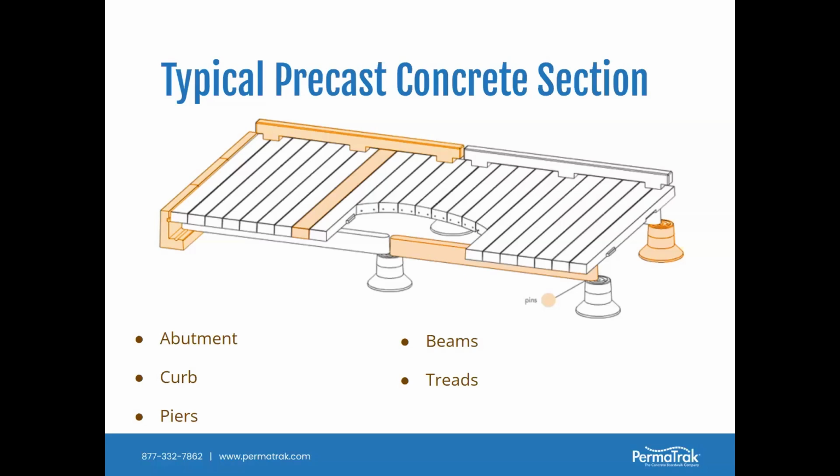So think about that original slide we showed you about where you put the boardwalk and what the impacts are to the wetlands. Think about how fewer piers is less impact, right? So that may become important to you. And then lastly, the perpendicular component, or the surface that you're walking on, is what is referred to as a tread. That is the plank, if you will. If you're familiar with timber boardwalks, that would be the plank. It would simply be a plank of concrete. And then typically a curb or a railing would be set on top of the system. So that's a concrete boardwalk system.